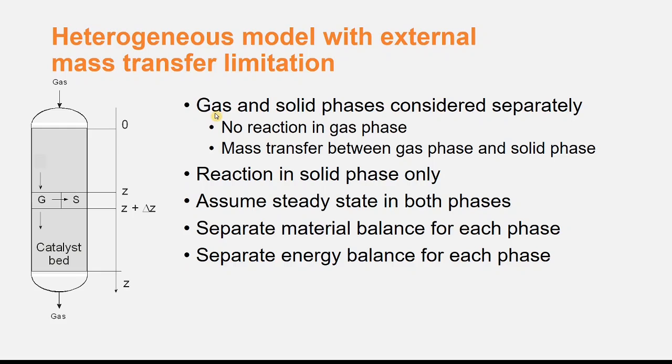In this example, there will be no reaction in the gas phase. There is mass transfer between the gas and the solid phases, and the reaction takes place only in the solid phase. We will assume steady state in both phases, and we will derive separate material balances and energy balances for each phase.